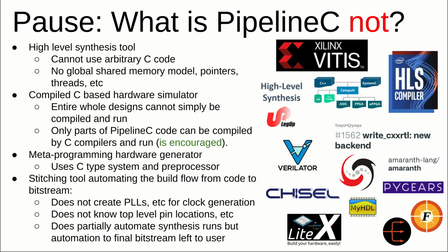And it's also not a stitching tool. So it's not just made for, I have this set of modules, I need to link them up to a bus or something and spit me out a system on chip. It's not doing any of the top level kind of instantiating PLLs or doing anything with clock networks. It doesn't know anything about the top level pin assignments you have out to your board or anything like that. It is doing synthesis and place and route in the background, so you do get some of that to use, but actually getting a bitstream out of your tooling is still left to the user.